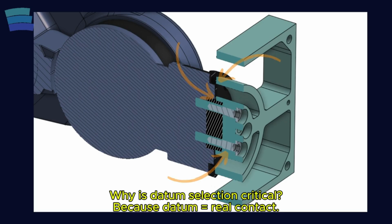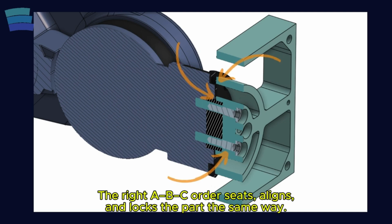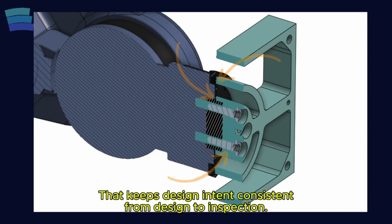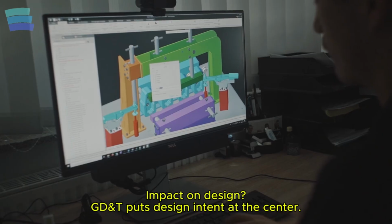Why is datum selection critical? Because a datum must represent the actual surface that contacts and constrains the part in assembly. A randomly chosen surface might look stable in inspection, but can cause surprises during assembly. The correct datum order seats the part in the same way, aligns it in the same way, and locks it in the same way every time. This keeps design intent consistent throughout design, manufacturing, and quality.